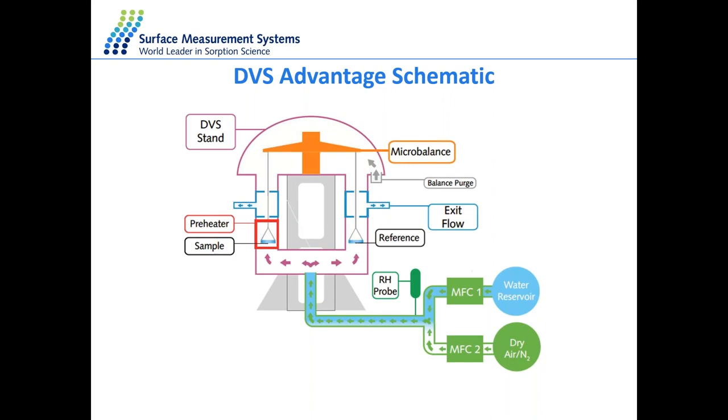And the other side is connected to the headspace of a bottle of water, and that will represent wet. The two gases will mix and push in front of a sensor that will read the humidity as a reference value, and then it will go to a sample and a reference chamber, which are connected to a microbalance. The microbalance that you see represented here is basically an old pharmacist balance with two plates. One side is sample and one side is reference.